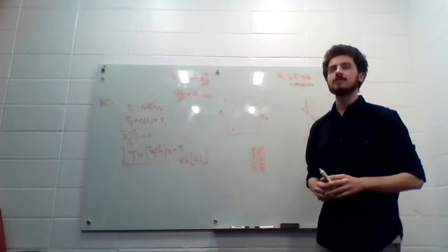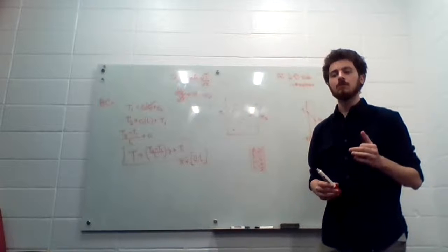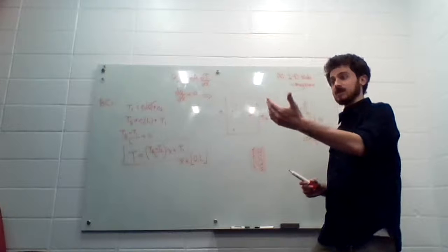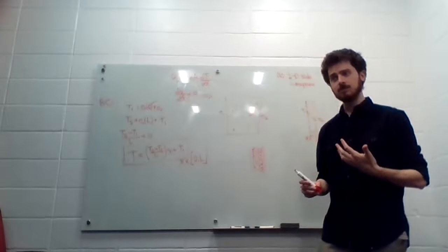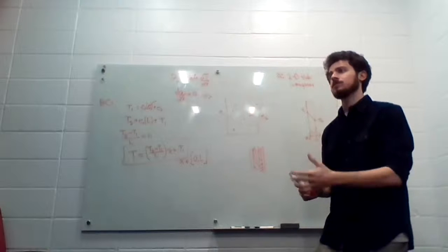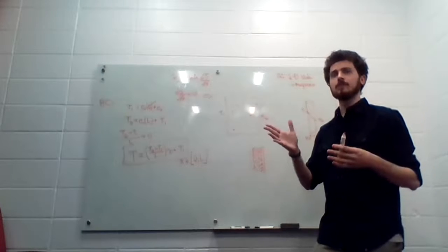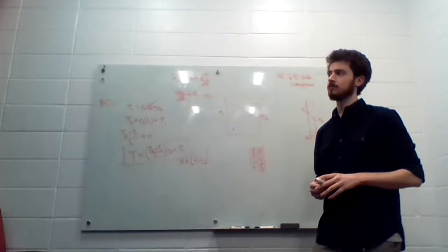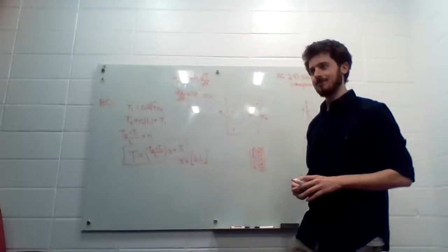So we would run two different tests, right? We want to know at a hot temperature, when it's hot outside, how much heat is going to be gained through those walls. And we want to know at a cold temperature how much heat is going to be lost through those walls. And we use those two numbers to size the boiler and the air conditioner, or I guess the air conditioner and the boiler in that order.